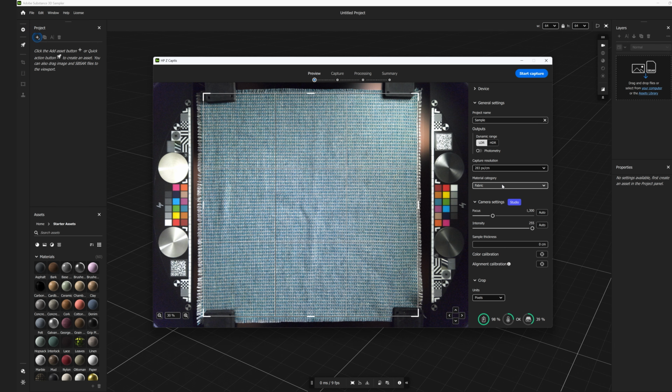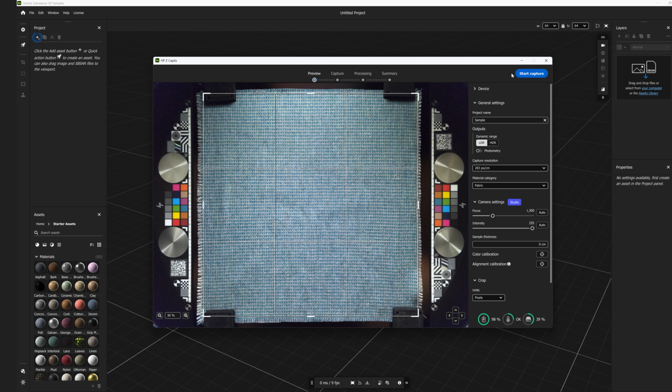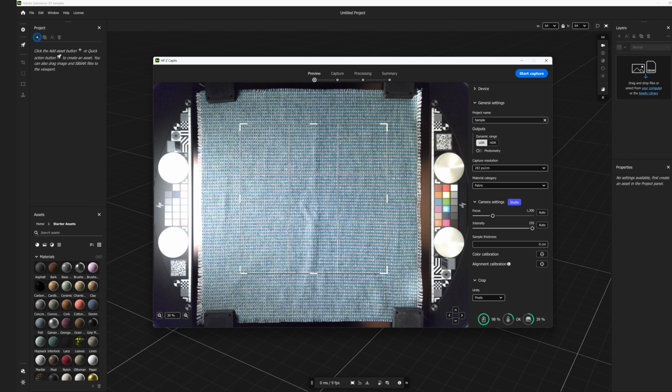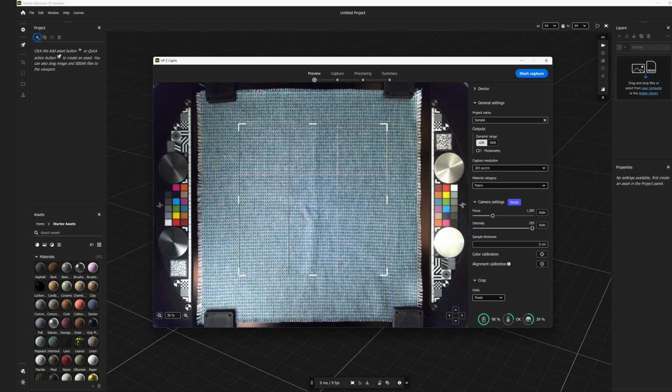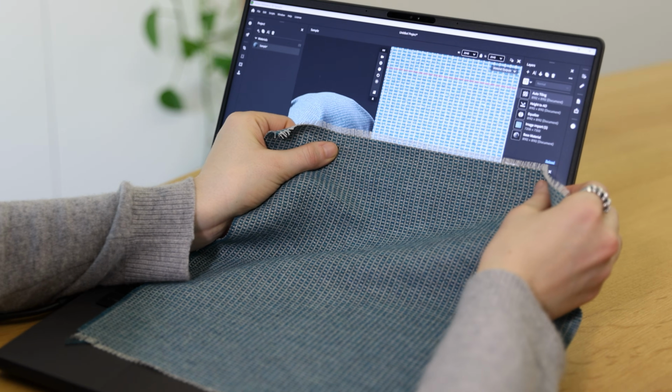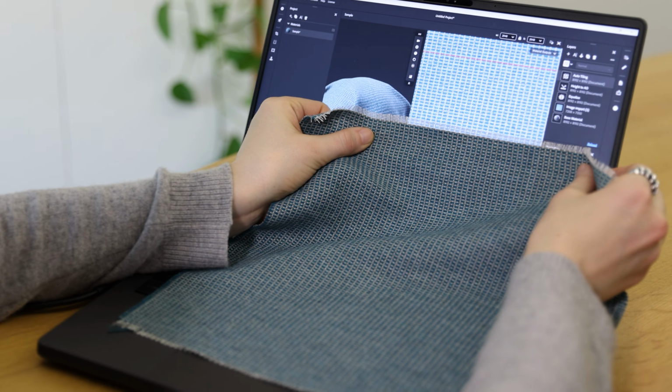The next important step is defining your region of interest. If you don't need the maximum capture zone, crop directly in the preview by dragging the slides and corners, or enter parameters in pixels or physical size. The system will automatically calculate the physical dimensions. A smaller region of interest speeds up the map processing while keeping the resolution square ensures consistency.